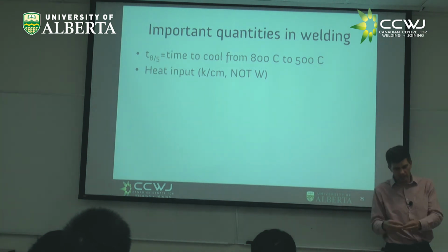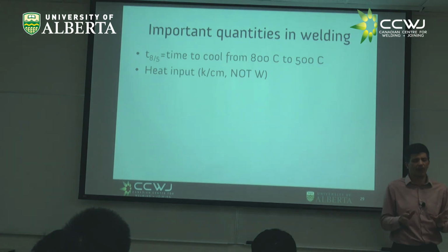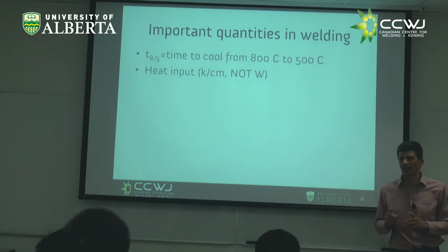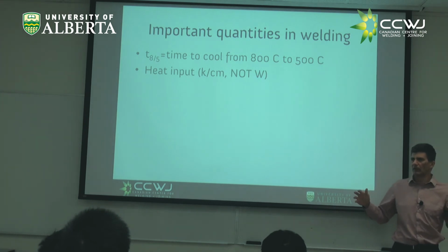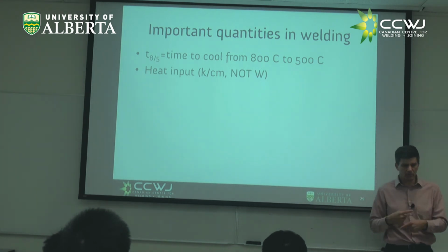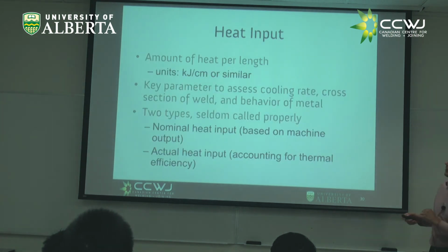And putting little heat, like in a stringer bead, means little time to cool down, right? Which is going to have a larger T85, something with low heat input or something with high heat input? High heat input is going to give us a long T85, right? So you start to see how all these things connect, and these things go together with the math.